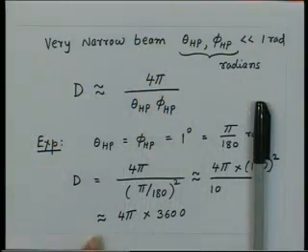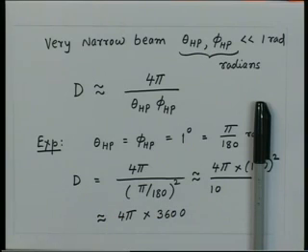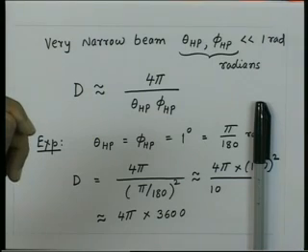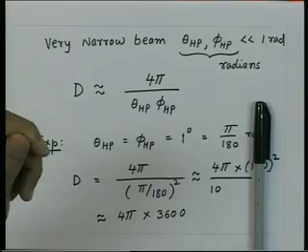So let us take a typical example. Suppose I wanted a certain radiation intensity which I would get with this antenna, and let us say the power I required was about 1 watt. So I take this antenna, supply 1 watt of power, and get a certain radiation intensity at a certain distance. If I did not use this antenna and used an isotropic antenna instead, I would require 40,000 watts of power to get the same radiation intensity in that direction.